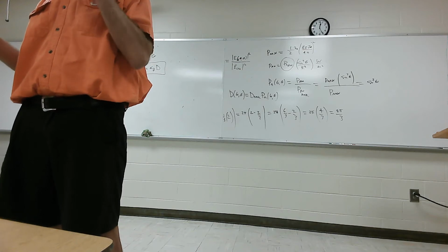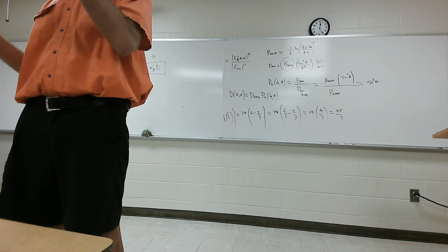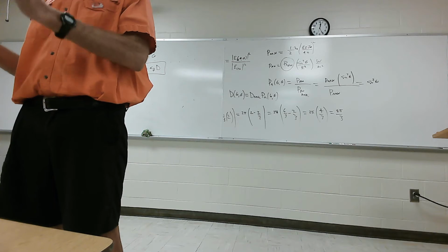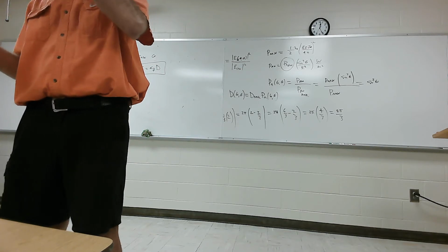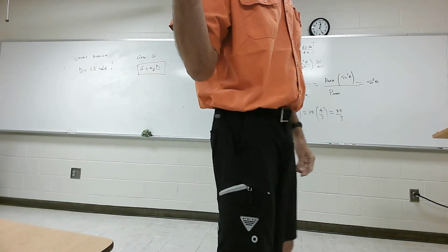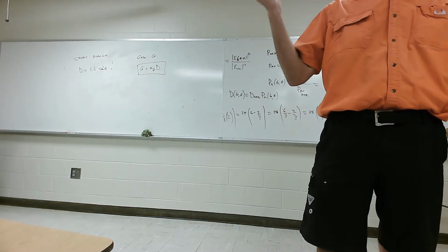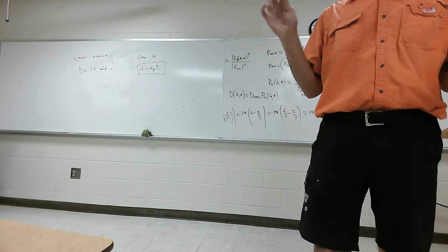Well, we had one that was causing this enormous inductance, that was causing a standing wave ratio mismatch, which is causing my efficiency to be horrible. Anyway, he went in and reheated that thing, removed it, and the antenna worked the way it should. But that was a scare of my life.